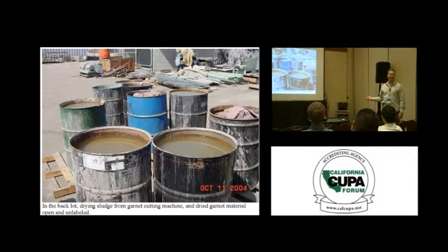And why is that? Because there's supposed to be things like freeboard in tanks. They're supposed to have high-level alarms, secondary containment. So there's more of an allowance for this situation than a container. Containers don't have to have secondary containment. They don't have to have high-level alarms. There's no freeboard level on it. So you're not allowed to do this. You ever see this at a facility? Yeah, okay, there you go.